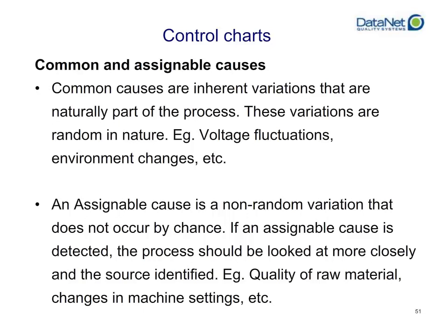So some examples of things that in a manufacturing environment could be an assignable cause include things like the quality of the raw material that you're using. One vendor gives you really, really good quality material. The other one gives you really bad quality or questionable quality material. And you see in the output of your process, then all of a sudden there's a shift. One material you're running at really close to target, and the next material you're all over the place. So that might be a source of an assignable cause.